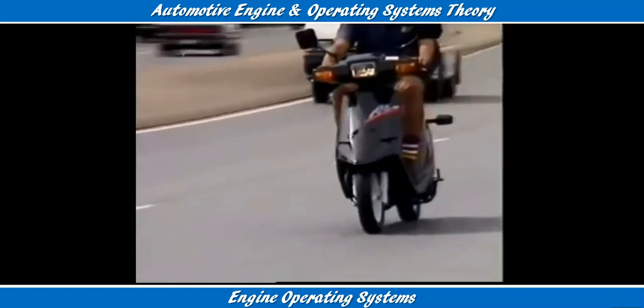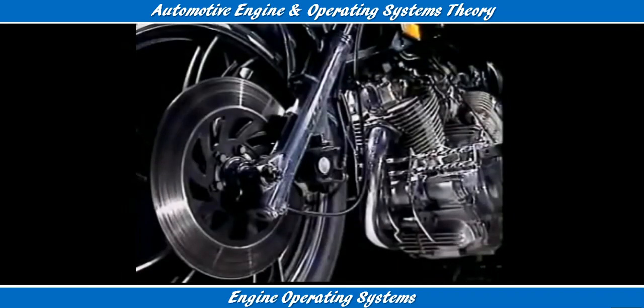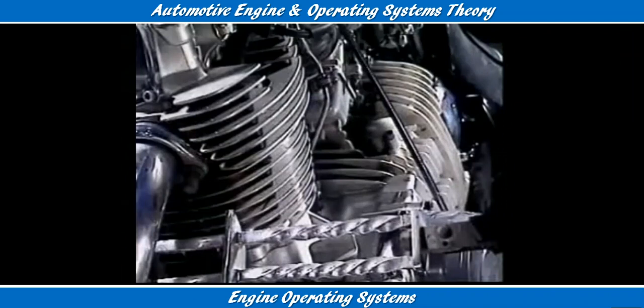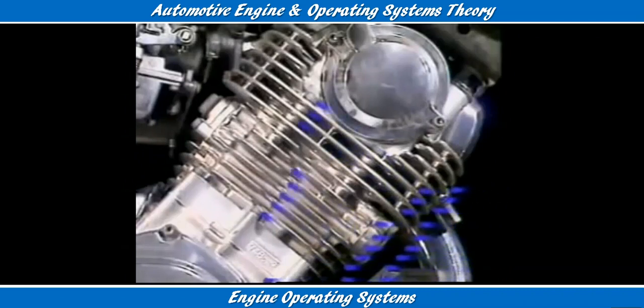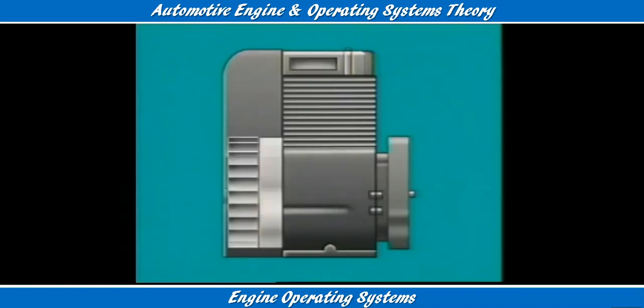Air cooling is common on smaller internal combustion engines. Some engines use cooling fins. Their design makes the exposed surface area as large as possible, which allows more heat energy to radiate away and be carried off in convection currents in the air. Some engines also use a fan to direct air over the fins.